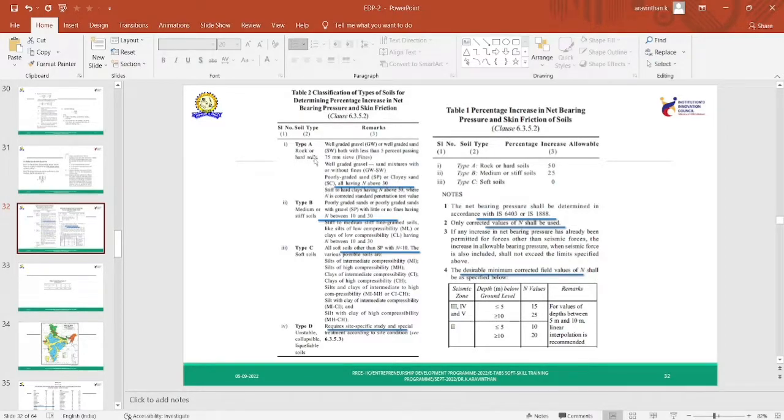So when you want to construct a building, first the designer needs a soil investigation report. Without a soil investigation report, we cannot start designing. So before a client meets a structural engineer, he should have an approved plan and the soil test report in order to proceed with the design. This is the conventional way. You do not skip this procedure.